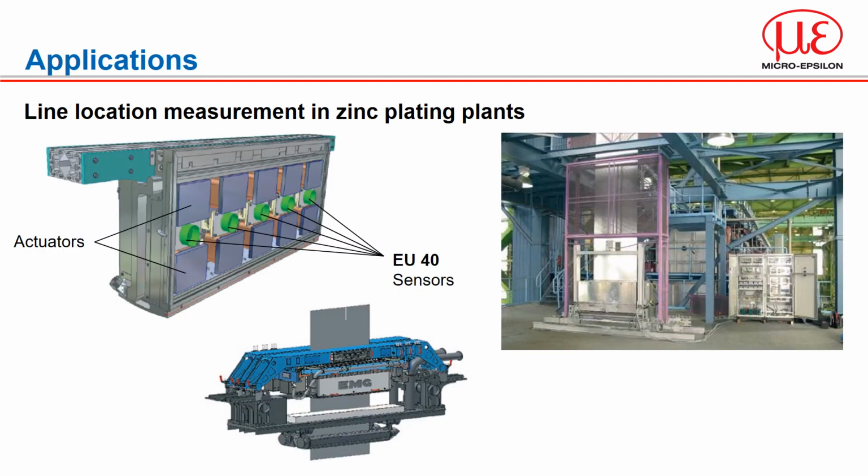The application of zinc to metals ensures longevity and reduces the chance for the material to oxidize. The coating process and thickness relies on the position of the base material as it passes through the bath and is controlled by a series of actuators. The strip position is monitored by a series of 40 mm range eddy current sensors spread across the material width, each providing positional feedback to the system to control the actuators guiding the strip.